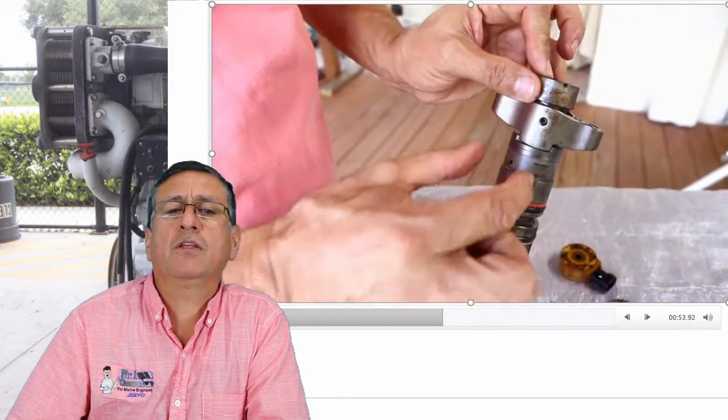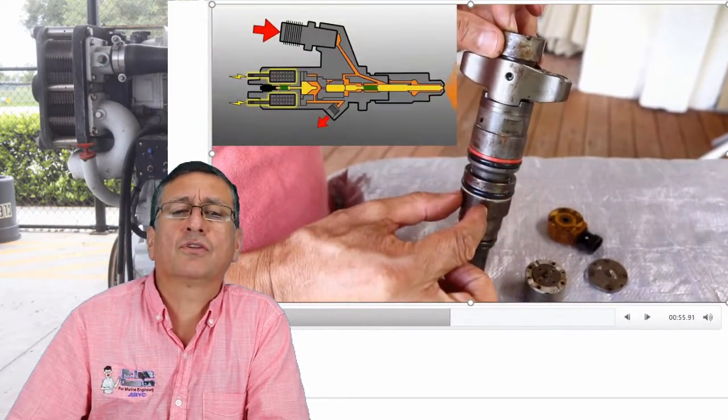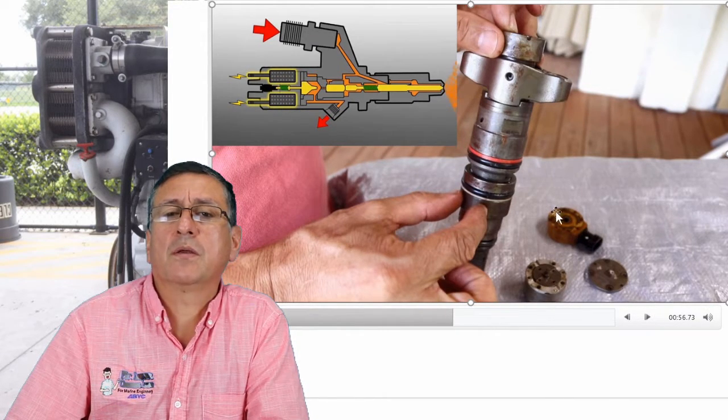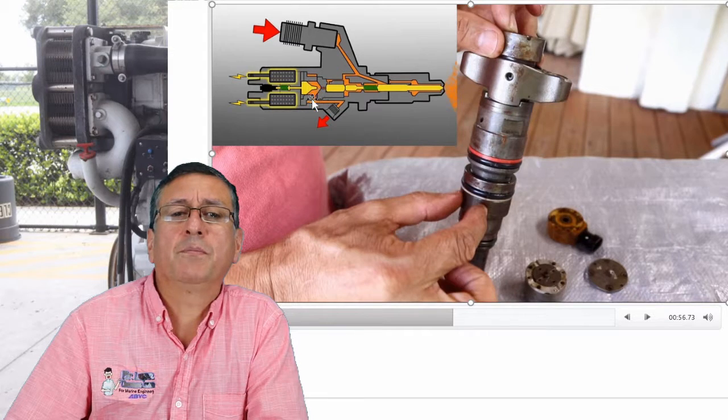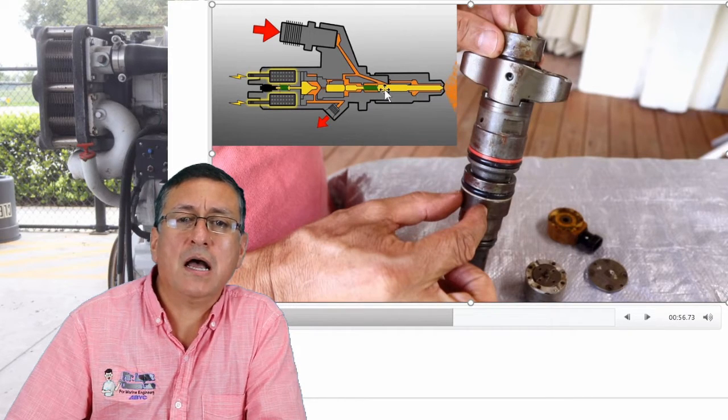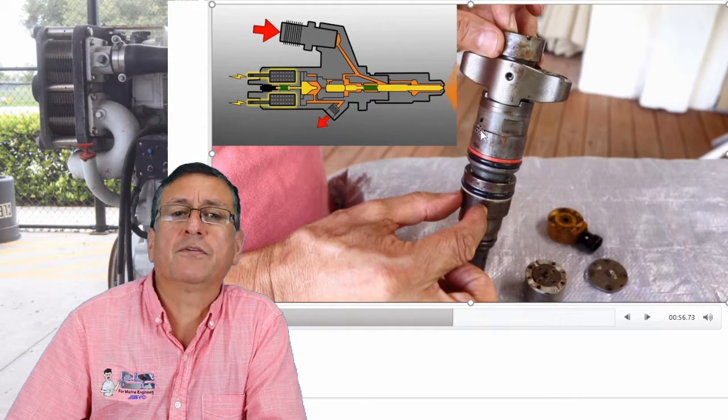Normally the fuel is coming over there. Internally, the construction is similar to the previous one. Look, that's the solenoid that we remove here. This is the pin with the washer. Those pin and washer are here, and the rest is exactly the same. You have a needle, and the fuel enters laterally over there, enters in the bottom, you remember, and produces the pressure, and when the needle goes up, the fuel passes and sprays the fuel.